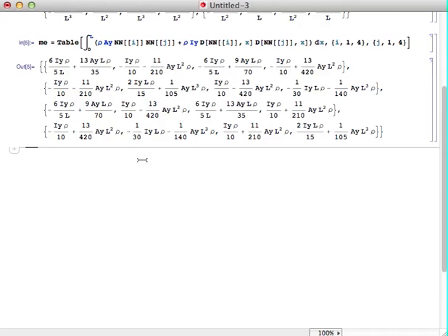Okay. So we're going to do the drop thing that I've done. I'm going to drop the first two. The mass and stiffness matrix are 4x4s, right? So the first two rows and columns correspond to those 2 degrees of freedom. So I'm just going to drop those.